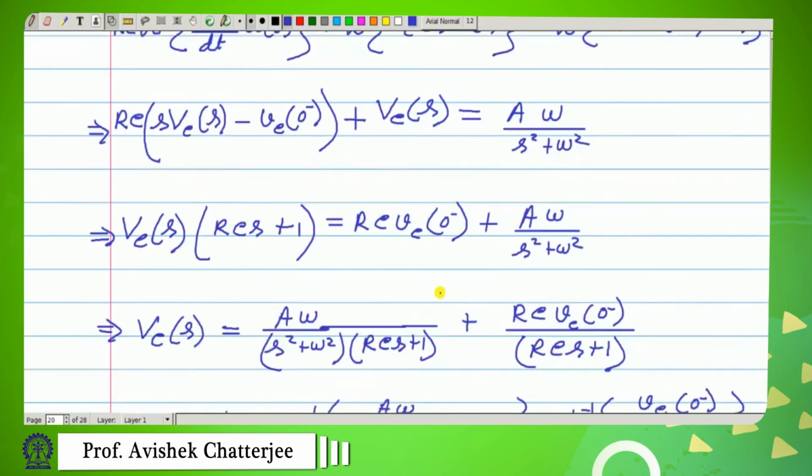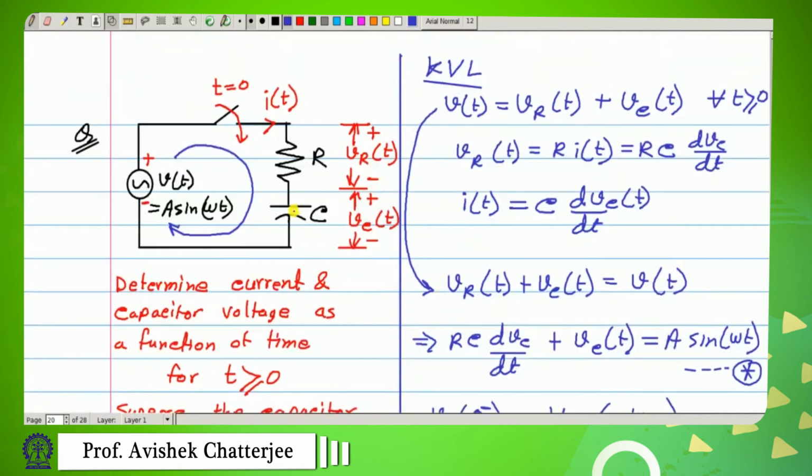This means that the voltage across the capacitor immediately after this switch is closed will be same as the voltage immediately before this switch was closed. That is because for this voltage to change, some charge need to come and get stored here in this capacitor. But for that we need some time, no matter however small that time is.